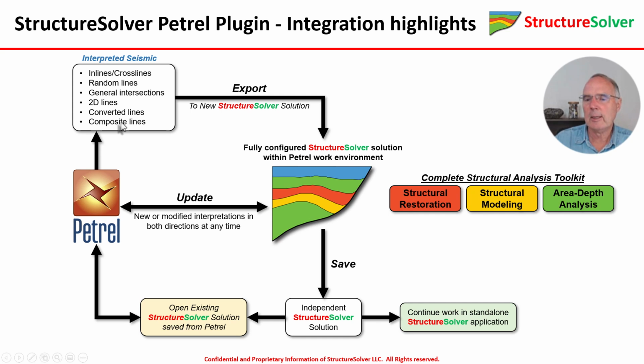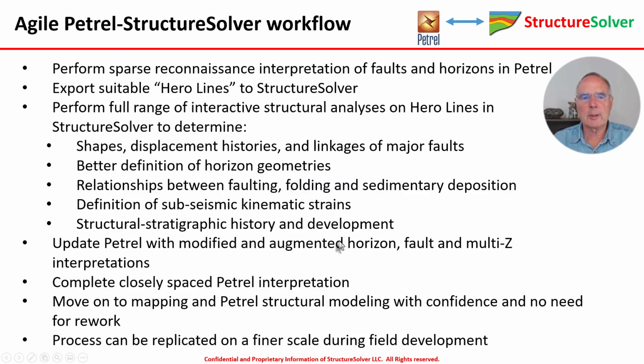So I showed how once you export from Petrel, you can perform a variety of analysis very quickly in StructureSolver. What we recommend as a workflow when you're starting out with a new 3D cube is, rather than jumping right in and doing a very close interpretation with auto picking and close fault interpretation, you perform a sparse reconnaissance interpretation of faults and horizons in Petrel. Then you export suitable hero lines to StructureSolver. A hero line is a key line that shows characteristic parts of the structural development. So you might have anywhere between 5 and 20 of those lines across the 3D cube.